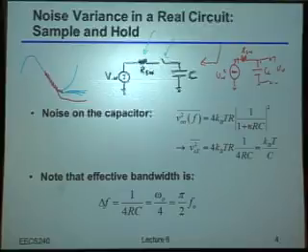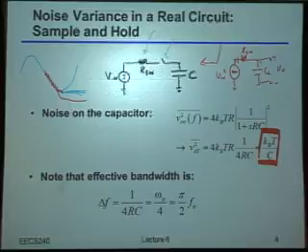Okay? So again, following exactly our procedure, if you look at the integral of this first order low pass filter, remember we said it was omega naught over 4? Well, in this case, omega naught is just 1 over RC. So the net integration of this is going to turn out to be 1 over 4RC. Okay? Well, here's where the magic happens. You take these two things together, you see that the noise is actually kT over C. Okay? Absolutely, totally independent of the resistance.